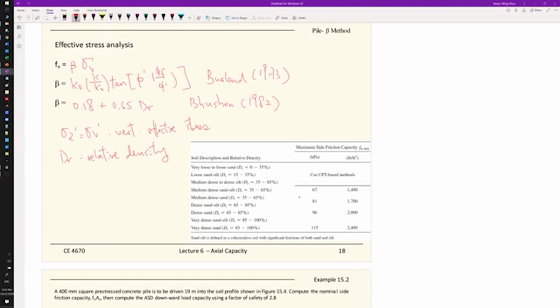And the bearing capacity for sand is always tricky. It's very hard to estimate for the use of foundations. So API again has recommendations on the cap, on what maximum side frictions are recommended to use. So when you calculate your side frictions, my advice is always ask yourself, does it make sense? Because at the end, the nightmare is overestimating the capacity of the piles, and that would cause failure.